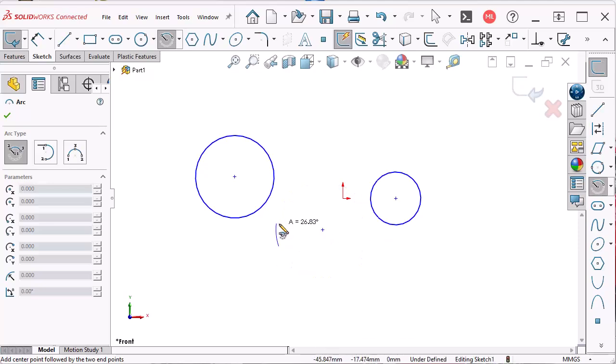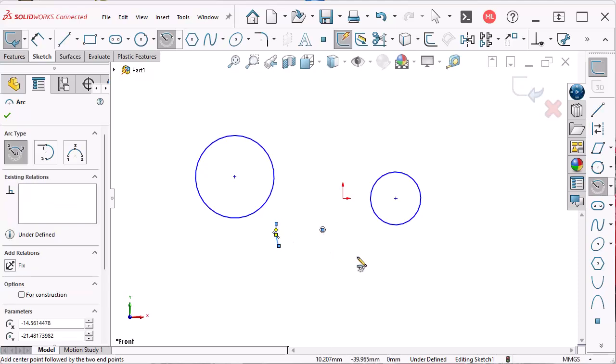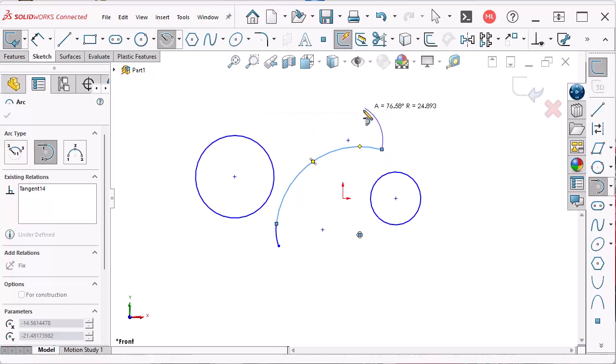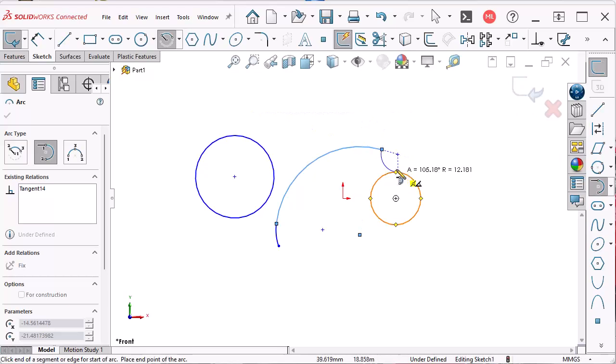And you'll have to probably play with that a little bit to get it just the way you want it so that you can predictably create the arc that you intend to create. A tangent arc comes off of any existing arc or line, or I believe ellipse or spline as well. You can also return and make this go anti-tangent, or I believe you can even make it go perpendicular. This all is dependent on how you move the cursor.